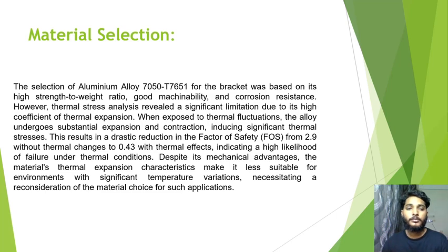This results in a drastic reduction in the factor of safety from 2.9 without thermal change to 0.43 with thermal effect, indicating a high likelihood of failure under thermal conditions. Despite its mechanical advantage, the material's thermal expansion characteristics make it less suitable for environments with significant temperature variation, necessitating a reconsideration of the material choice for such applications.